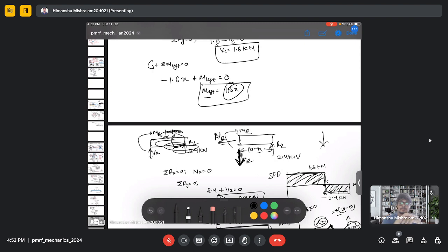But for a bending moment case, the change is either linear, which is proportional to x, or it could be non-linear as well. For the varying load, it could be non-linear, which will be proportional to x square or x cube. So if you have a varying load, then the bending moment you will get some kx squared or even higher kx cube. So it will look like this compared to this. So this is our present case.